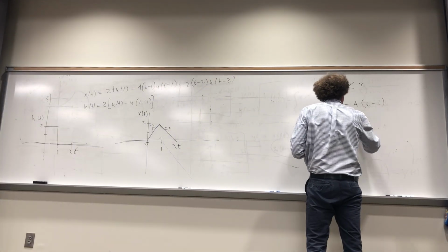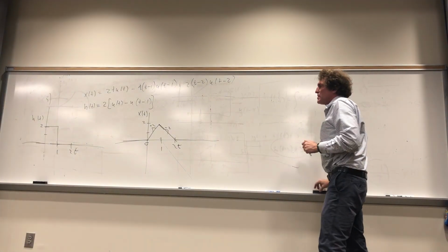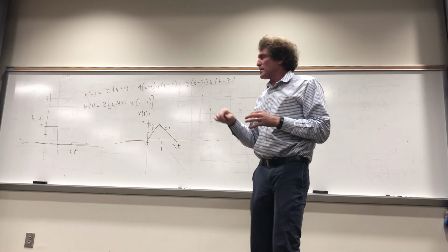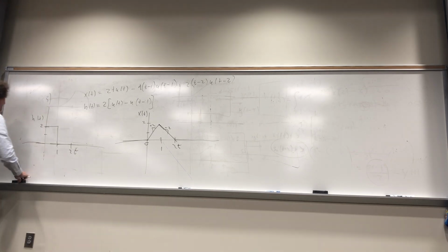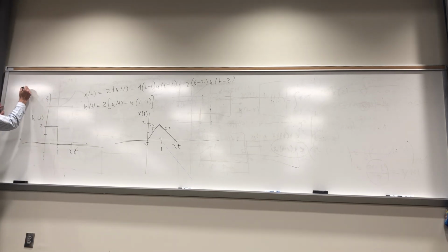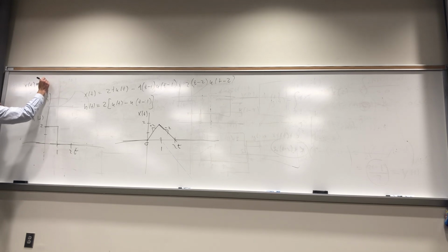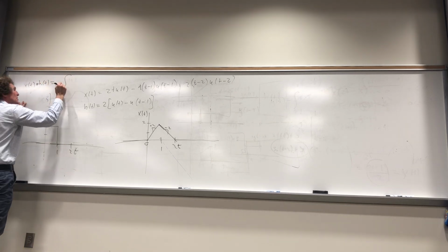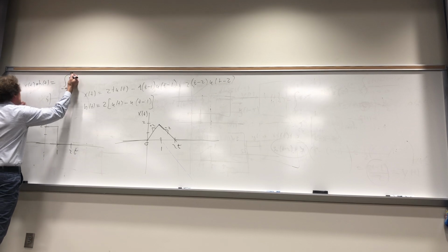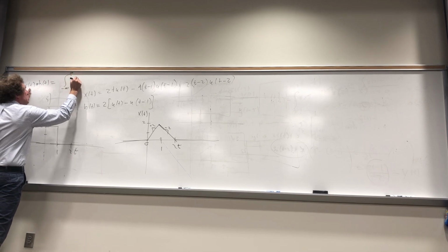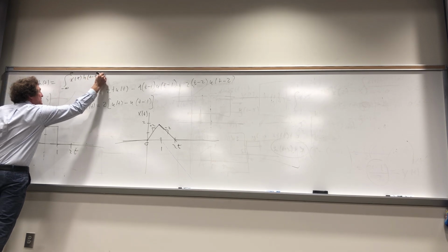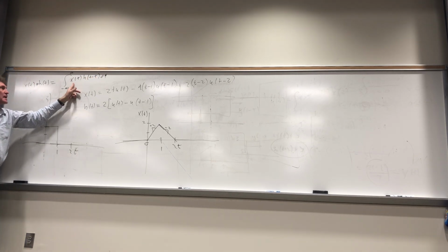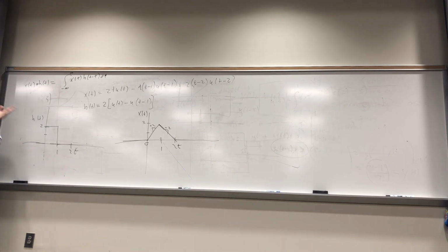So when we're convolving these two functions, I've told you the way you do it, the one in convolution, again, I'll put it up here, is defined as when we have the convolution of two functions, x of t convolved with h of t, that's really the integral from minus infinity to infinity of usually the first, and you can put tau here, times h of t minus tau d tau. But it doesn't matter if this is h and this is x. The order does not matter.